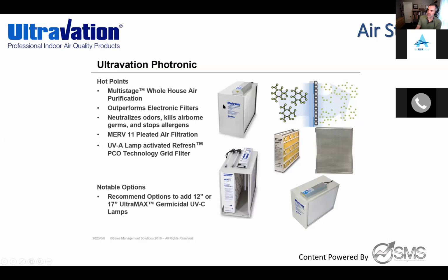So standalone, as the box is, technically it's not perfectly matched to what ASHRAE wants. As soon as I put those accessory lamps on and put UVC over the coil, cool, I'm aligned with ASHRAE guidelines. Now I'm getting the best of all worlds. Granted, it's still not an in-duct solution for the supply, but you're taking care of a lot of air purification before you even enter the HVAC equipment with something like this. So you're combining UV and filtration all in one.